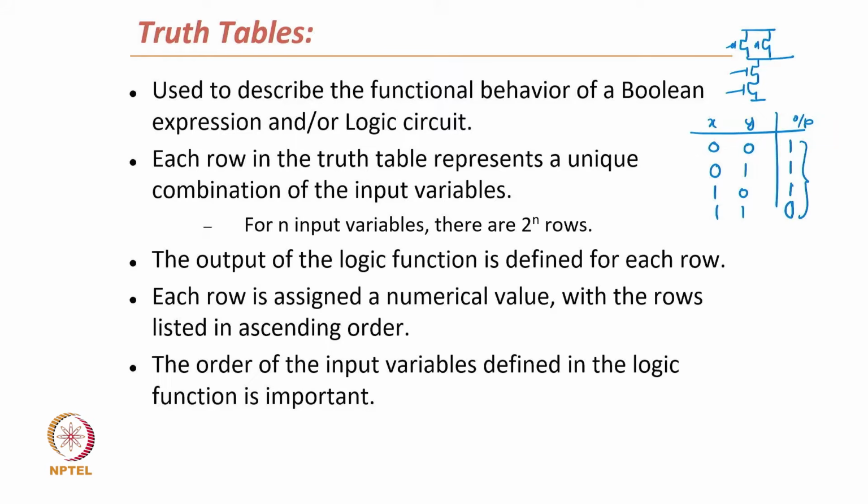So, in this case, this NAND gate has its own truth table which is used to describe the behavior of this circuit. So, we make these circuits using PMOS and NMOS, and then we analyze what is the truth table which we have implemented using this gate.